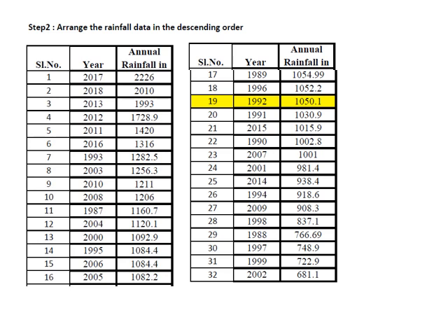My very idea is to find out what is known as a dependable rainfall. Because you cannot design the bund for the highest rainfall, which is 2226 millimeters, nor can you design the bund for the lowest rainfall. So somewhere a via media between the highest and the lowest rainfall has to be taken. For that, we know what is known as a dependable rainfall. Dependability is generally taken around 60 to 75%. Taking the lower side, we take dependable rainfall as 60%.